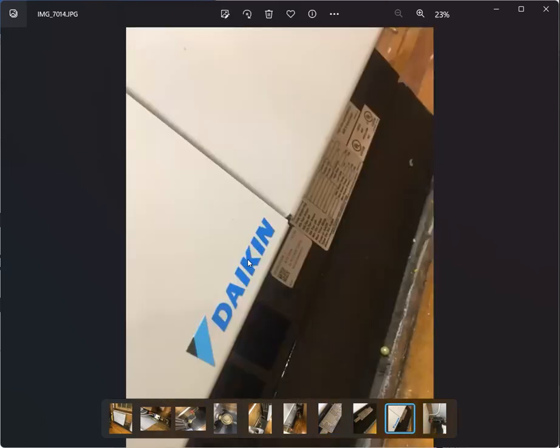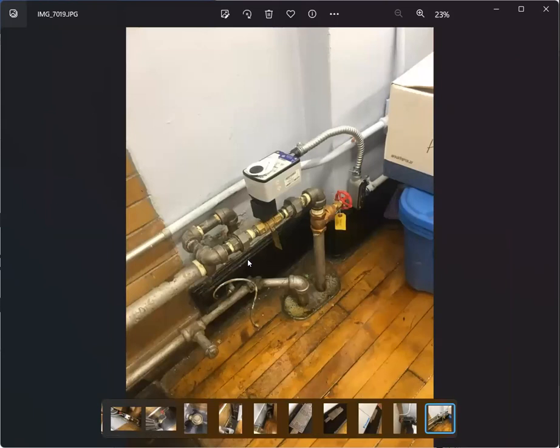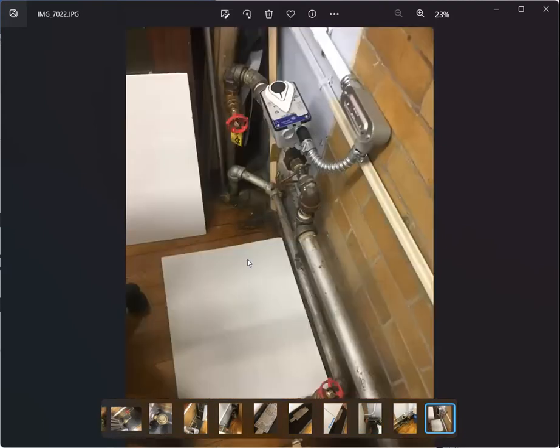As much as you could, take a photo and evaluate everything after the actual walkthrough and inspection. Identify the model and the manufacturer of the unit that they have installed. And this is the supply and return for the ventilating unit in a particular room, the assembly of the new control valve. The control valve is only in the supply line. So is this the hot water line that will heat up your radiator here?